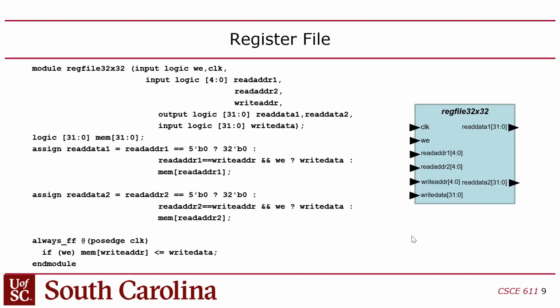Alrighty, so I showed the register file design. So this register file has a RAM array here. Remember that when you declare the RAM array, it's opposite of like everything. You put the width first and the depth second. Don't do that in C, or Python or Java.